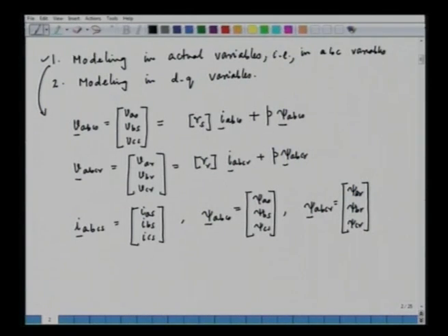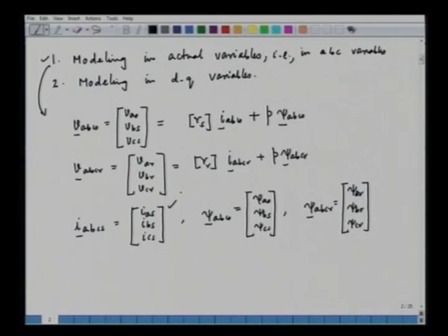So, this is the equation for the rotor, and the stator and rotor equations will be 6 equations, 3 equations for the stator and 3 equations for the rotor, and we have to solve these equations and find out the values of the stator currents, IAS, IBS, ICS, and the rotor currents similarly, IABCR, that is IAR, IBR, and ICR.